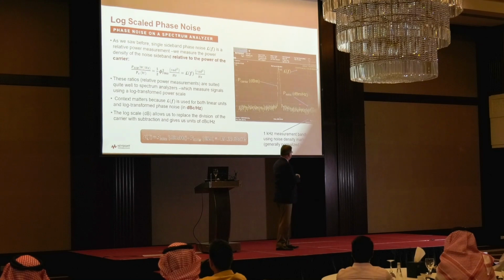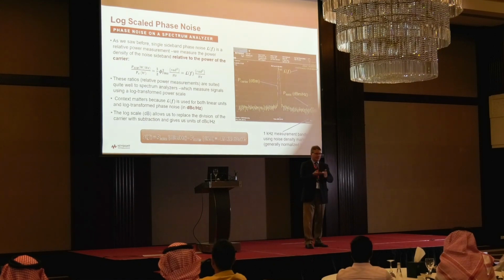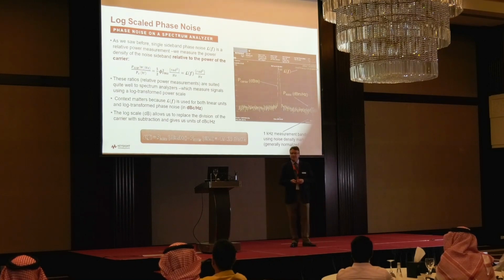And again, these measurements are typically made at a known offset. And if we want to get the integrated phase noise that I described before, we would be measuring all of the power all along here relative to the carrier. But typically it's made at a specific offset, 1 kilohertz, 10 kilohertz, or could be 100 megahertz, depending on what the requirements are that you have for your application.